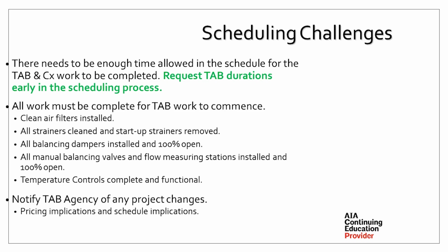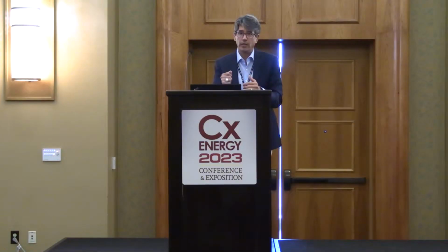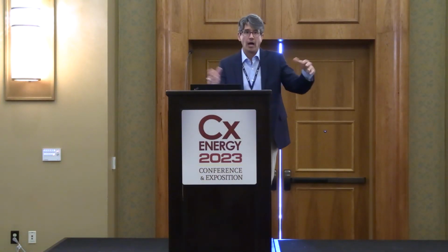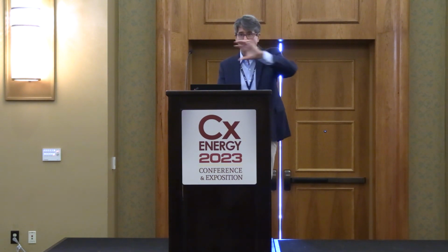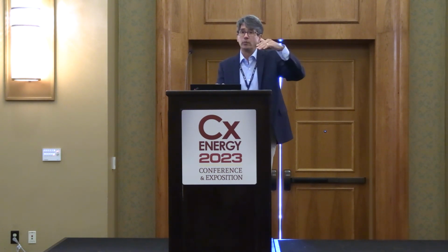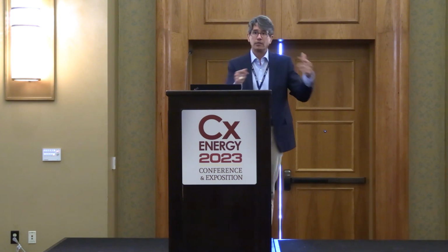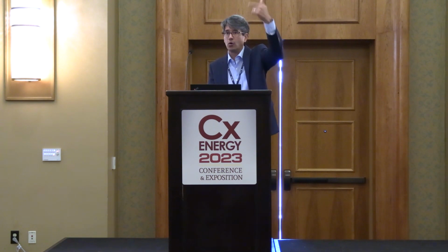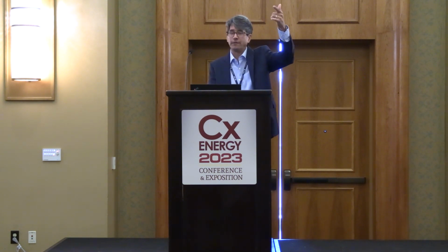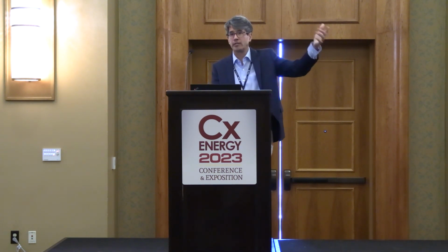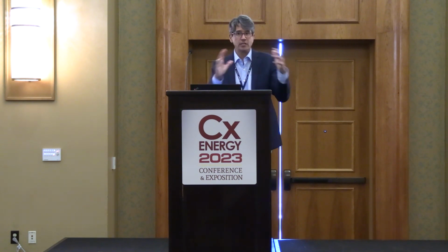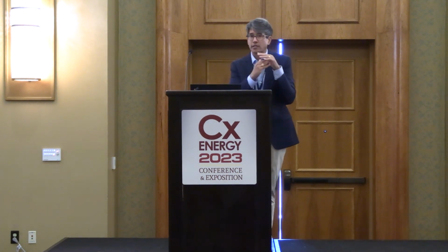So if this air handler serves floors 1, 2, and 3, we're going to finish floor 1, occupy it, then we're going to go finish floor 2 and occupy it, et cetera, et cetera. What are we going to do to be able to have that system operate to serve floor 1? Isolating it from floor 2. So those different things, when we get into phased jobs, area type projects, if that HVAC system doesn't match up to how they want to move in and how they want to utilize the facility, call a timeout.